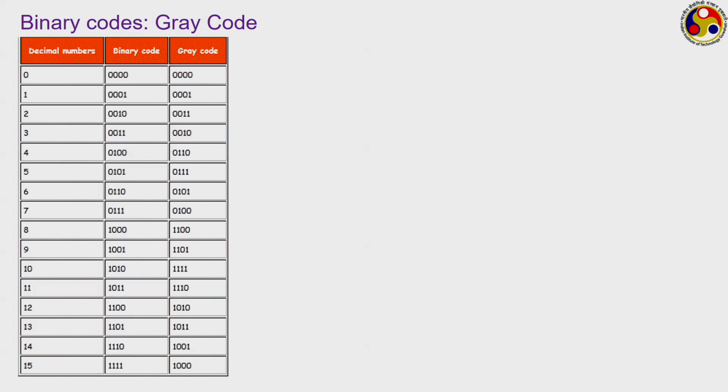Again we are talking about a 4-bit register. So, 0 to 15 are the decimal numbers which can be stored in a 4-bit register, because 15 has a binary equivalent of 1111, and logically this is the largest decimal number we can store in the 4-bit register. Think about BCD, there the largest decimal we can store is 9, but in case of gray code we are storing all 0 to 15, that is all 16 digits, but we are not following the binary format at all, we are following a different format like shown in this table. I shall be coming back to this number format very shortly.